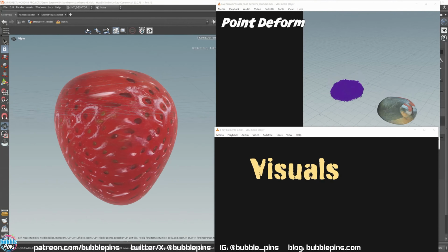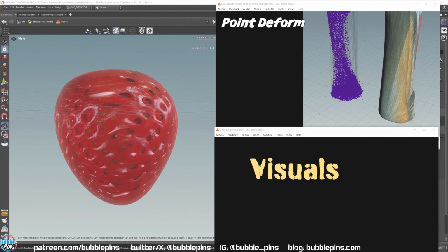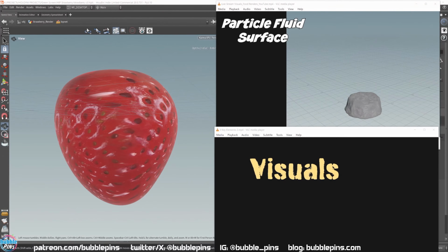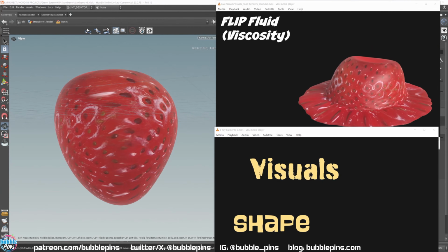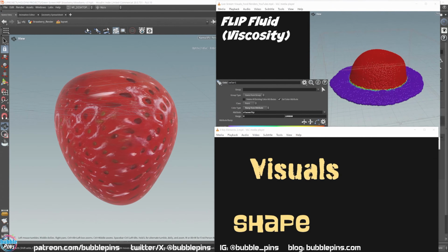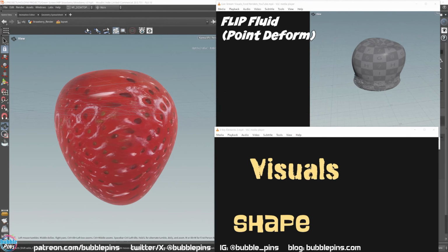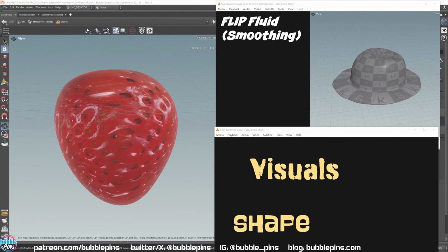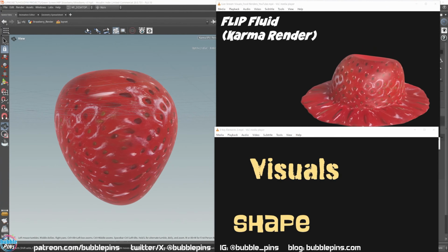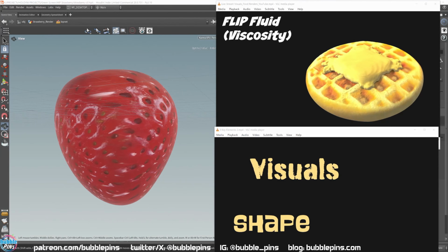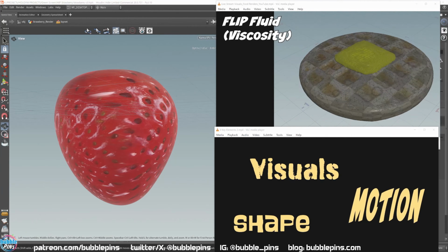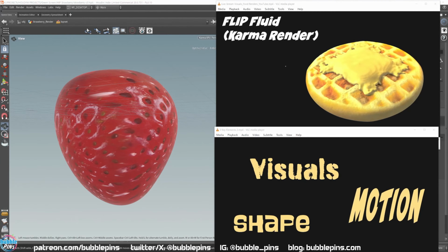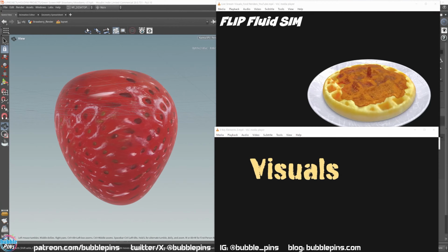In the vellum grain simulation, there were so many obstacles, mostly in the jittering, and how to stabilize the vellum grains into something you can actually use. The vellum grain simulation is nice and fancy, but at the end of the day, you want to transfer that simulation onto a geometry where you can pull apart the grains, like a cheesy or creamy effect. You want to convert the simulation into a mesh that you can actually render out.